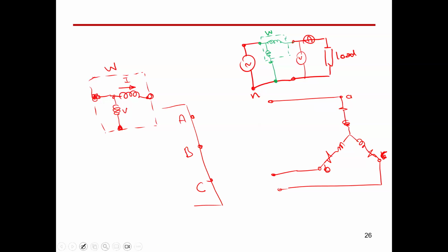So I'm going to draw the wattmeters in different colors. Start firstly with this color. So I can say for the first phase, this is going to be the current coil, and the voltage coil can be connected in parallel with the load. So this is a neutral of my load. So I can simply connect this to the neutral point here. And this would be our first wattmeter. And this is going to be wattmeter for phase A.